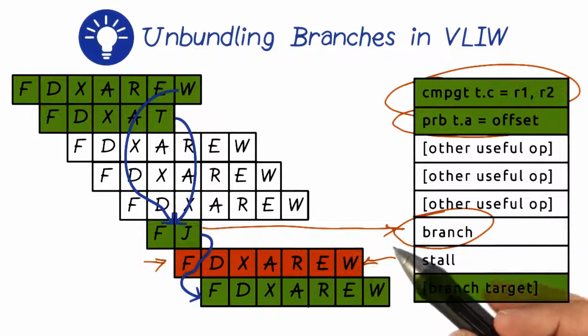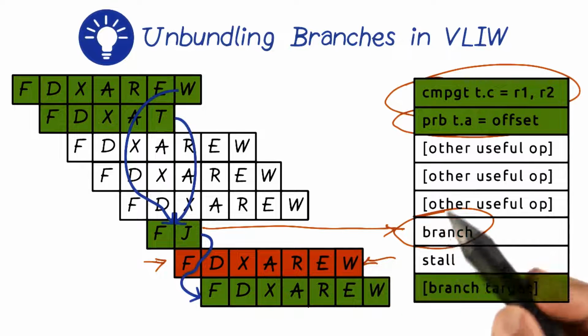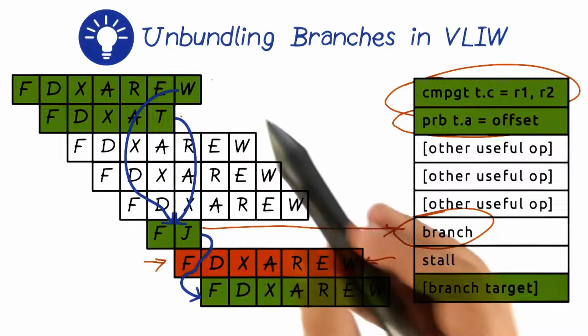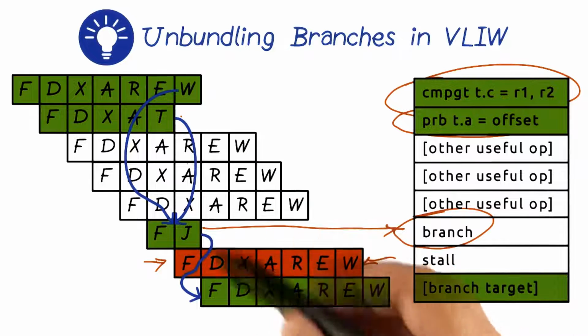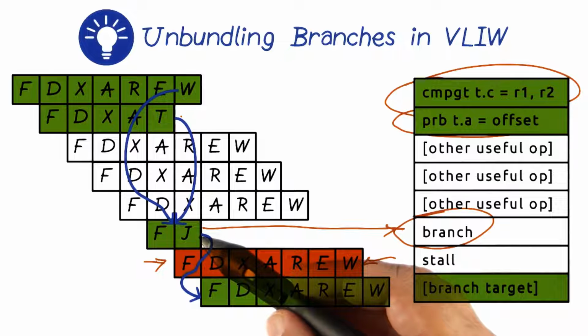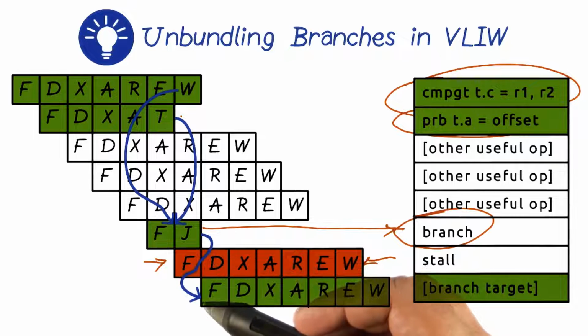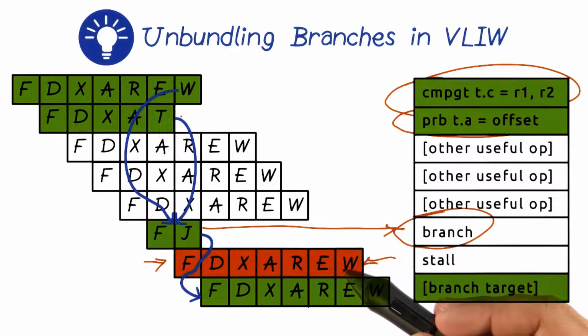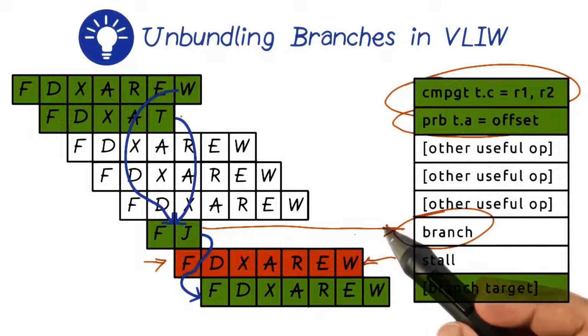You might wonder why the delay slot is so minimal here. You can see that the branch target is also known at this particular point, and so is the condition. So we can start fetching the instruction stream which is at the right destination and keep it ready. Therefore, once we take the jump, we have minimal work to do to just transfer the control to that particular PC address. And that is why the delay slots here is just 1, unlike 5 delay slots earlier.